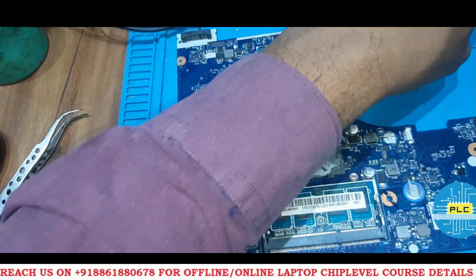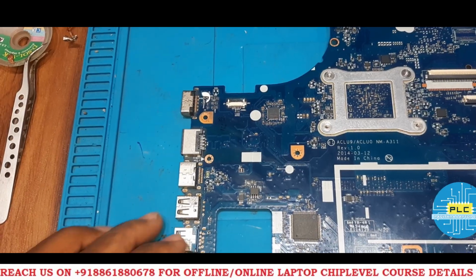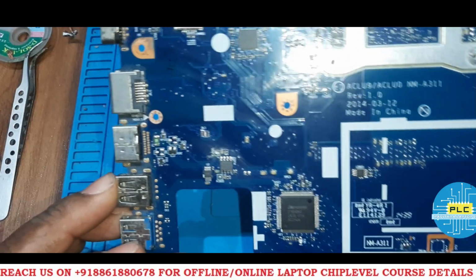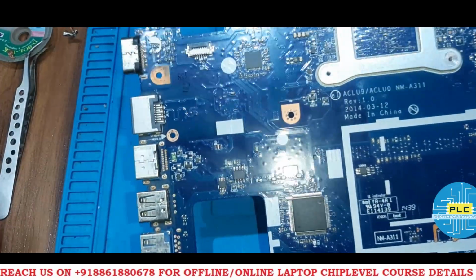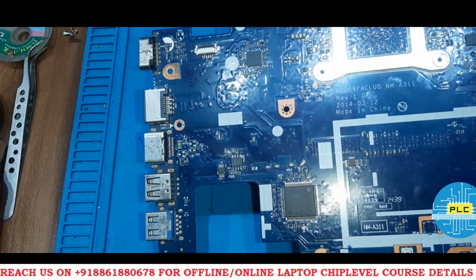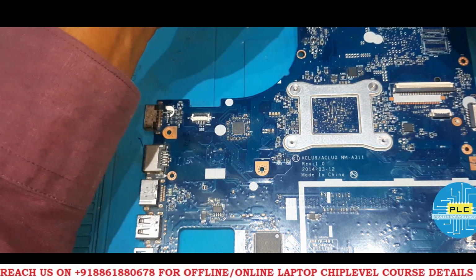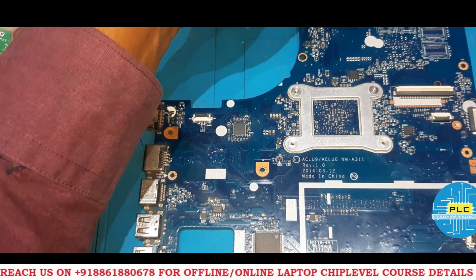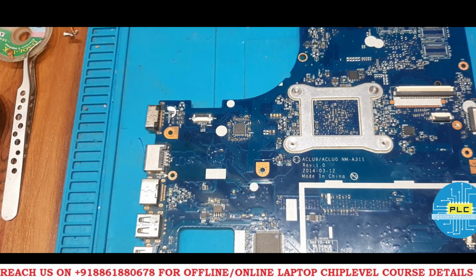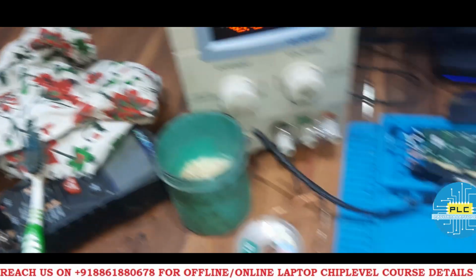So next we'll remove some other jumper. Now I removed PJ604. Actually the voltage name is plus 1.5 VS. Now I'm going to connect this. So what will be the result? Just a minute. So I connected. The result will be the same, 0.088, not much difference.